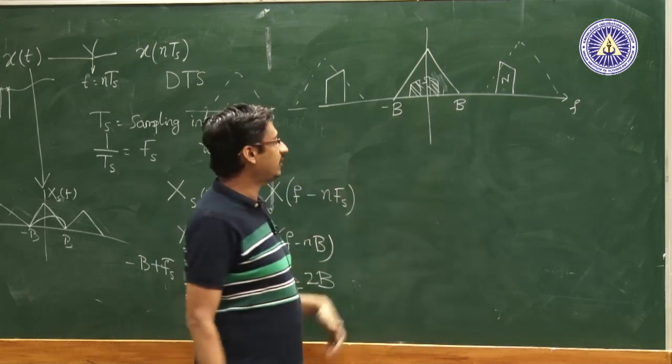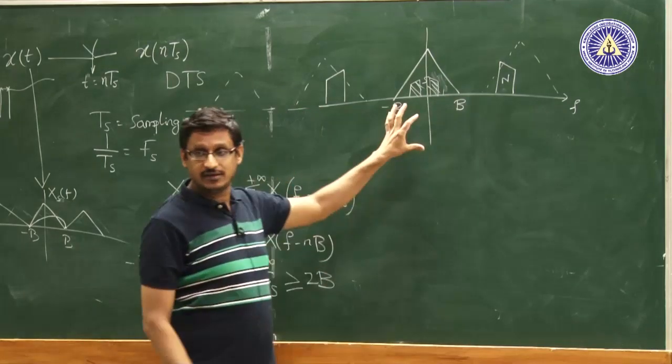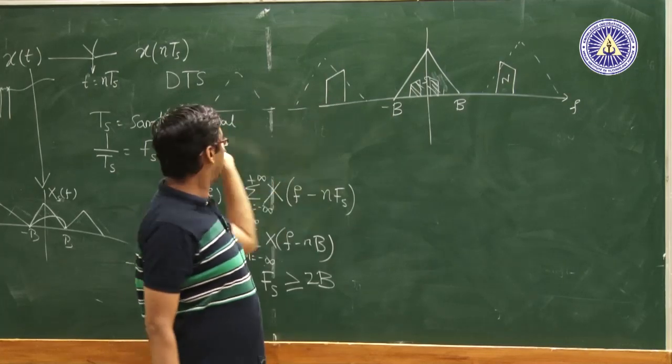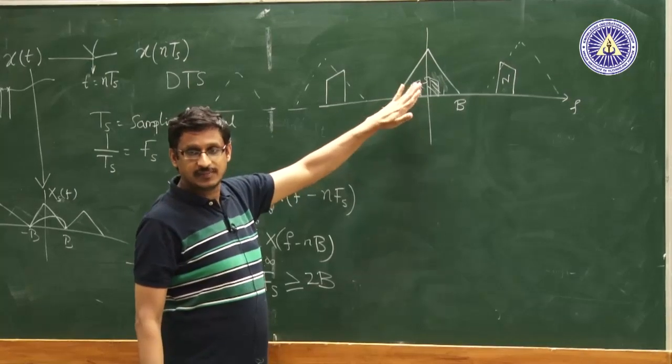So, this means that you cannot distinguish signal and noise in this bandwidth, and therefore, what you have done is sampling or converting an original signal which is still noisy, but after being converted, you cannot recover the signal correctly, right.